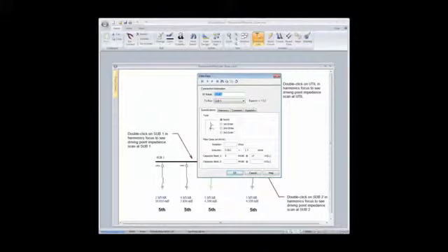Now, in EasyPower, this is going to be predominantly what we call a positive sequence or balanced simulation in the harmonics. We do allow you to use zero sequence, but in this case, I'll tell you that the capacitor banks inside EasyPower are all ungrounded. And so because of that, let me get some notes up here. Let me change to Microsoft Word.